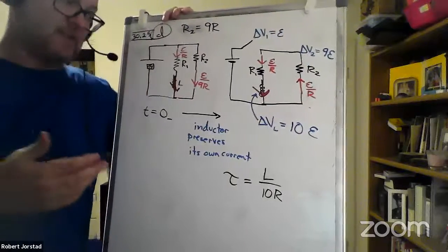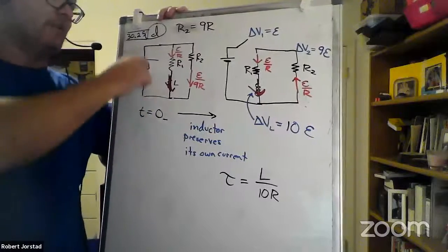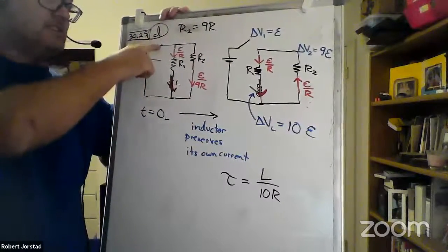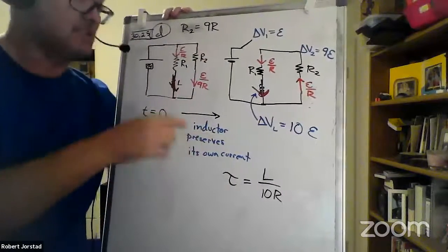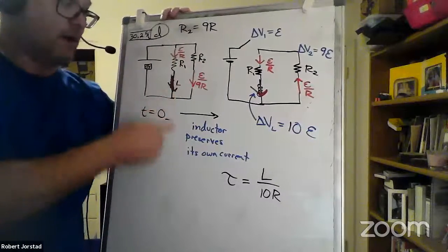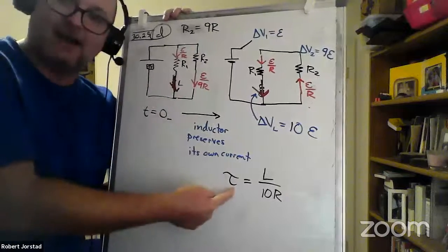Information about electric fields propagates through the wires at the speed of light, so on the order of nanoseconds to get around the information. So when you open this switch, the current in this branch, if there's truly negligible inductance, would basically go to zero in the order of nanoseconds. Whereas this current will persist on the order of 5 tau.